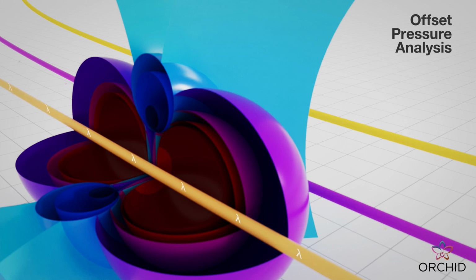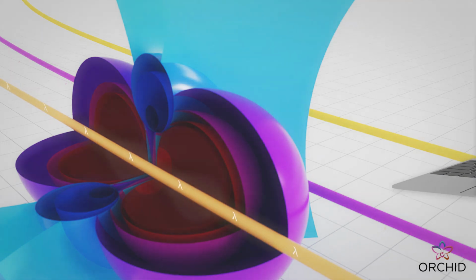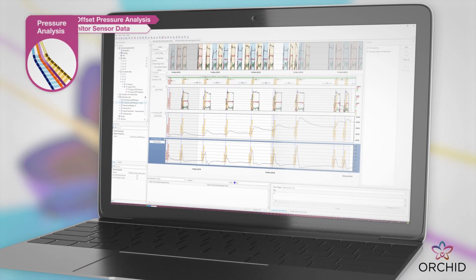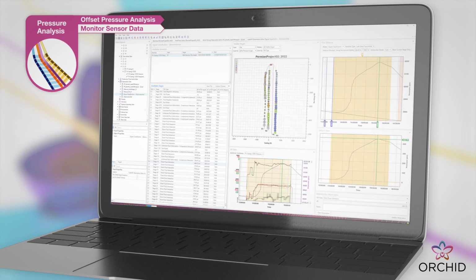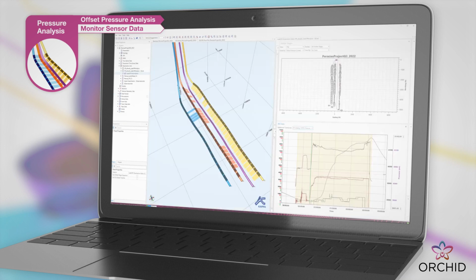Orchid makes looking into this data in detail quick, simple, and painless. Being able to extract the first derivative seamlessly on an interactive plot or analyze the primary data, the user can determine the volume to first response, define the fracture-driven interaction type and magnitude, and assess the severity of those interactions. With Orchid, VFR, magnitude, and the type of interaction can be clearly represented in 2 and 3D views along the wellbore.